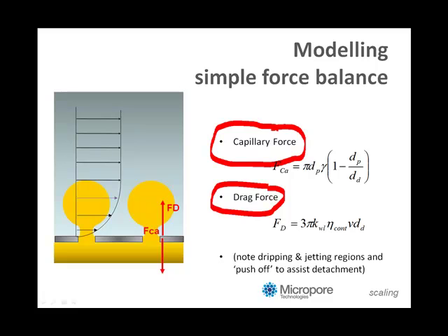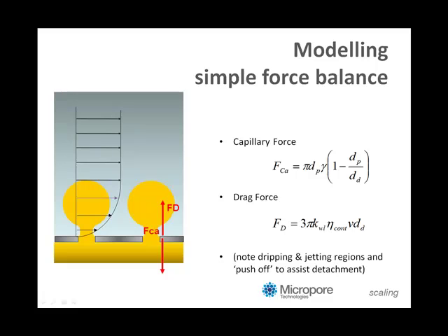And if you inject the drops reasonably quickly, then you'll move from what's called this dripping regime, drop being produced, drop being produced, drop being produced, into a jetting regime, which is where the jet comes out of this membrane pore in a much faster way. So productivity obviously increases when you're jetting, but the drop size distribution normally suffers, normally becomes wider.